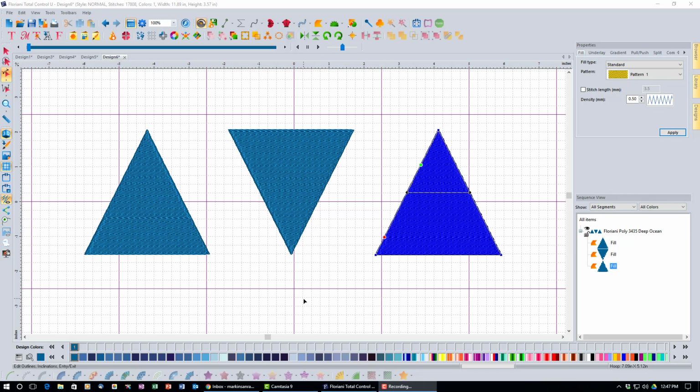So I've just done something simple here. If you want to do it to your whole design, of course, whatever you select, it's going to optimize the start and stop points. Now, if you would like to do all three of these things, so you want to invoke our entire set of 3 sequence and color sorting optimize tools, the proper order to do this in is to first do your color sorting, then do your optimize of your sequence, and then finally do your start and stop point optimization. So again, you would do color sort first, followed by your sequence, and then your optimize entry exits.